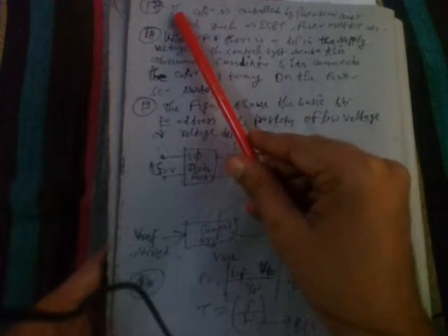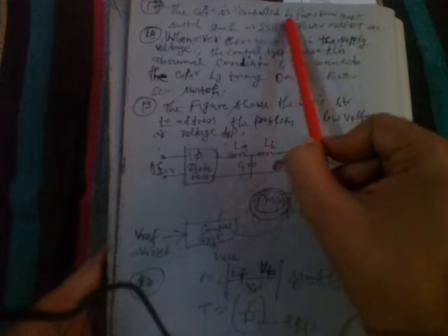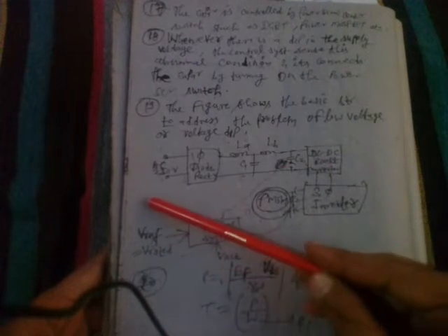17. So the capacitor is controlled by a power semiconductor switch, right? You see, this is the basic circuitry that we have worked upon. This is AC supply of 230 volts. This is a single phase diode rectifier, LA, LB and C1. This is the filter circuit to remove the ripples in the DC output of this diode rectifier.